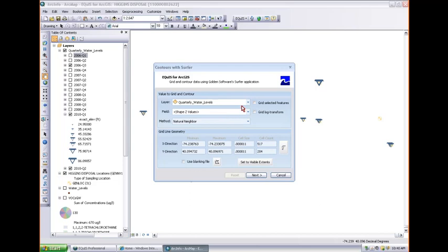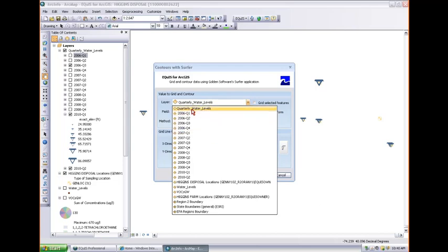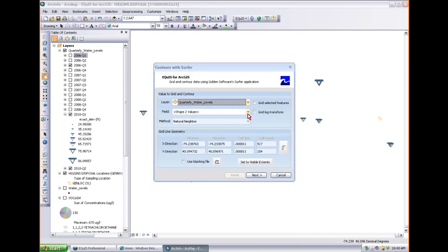So here, when you want it to operate on all the sublayers, you pick the top level one, the way I had it work. And then again, we'll pick exact elevation. We'll make this 517, which is a little overkill, I think. We'll just make it like 100, or maybe a little more.